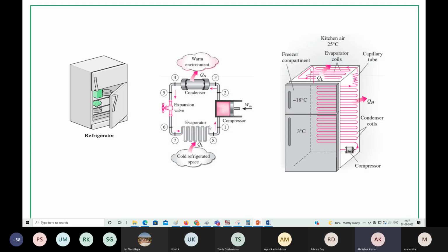So this is, in case of your split AC, the indoor unit, right? That is this component. The rest of these three are in our outdoor unit. Here in our indoor unit, when it is absorbing heat from the room, the liquid refrigerant is becoming vapor. This vapor is going to the compressor, where it is compressing. Then here it is condensing.